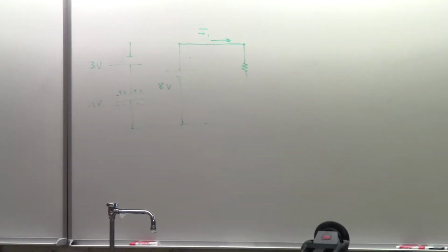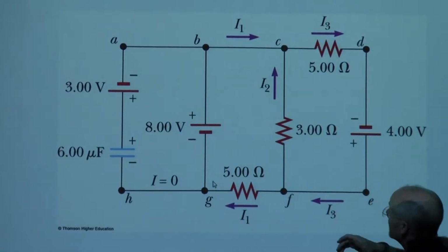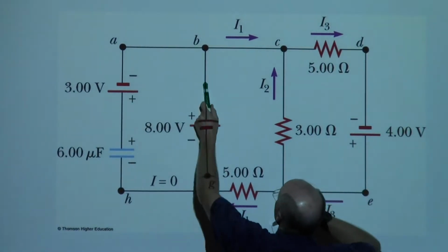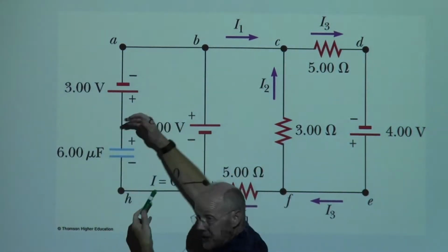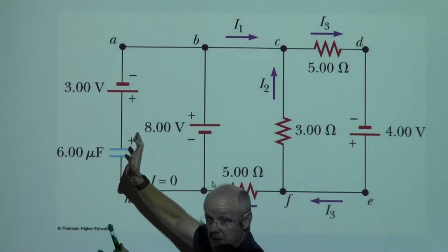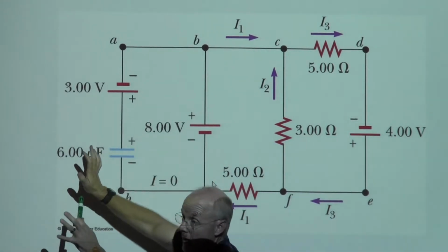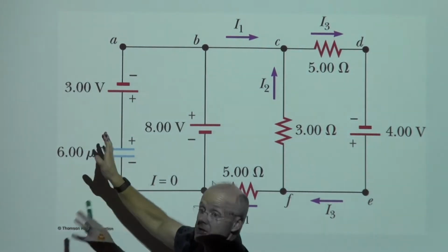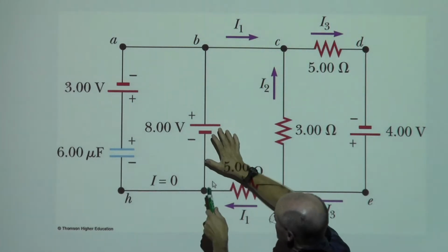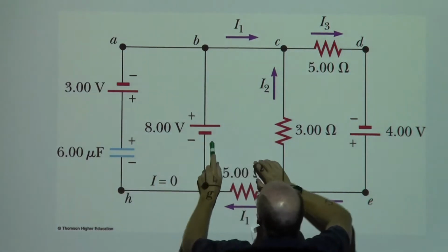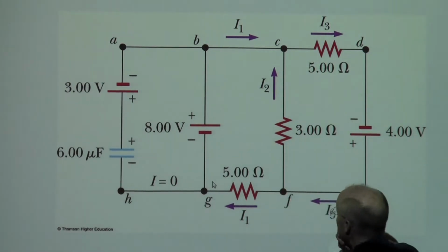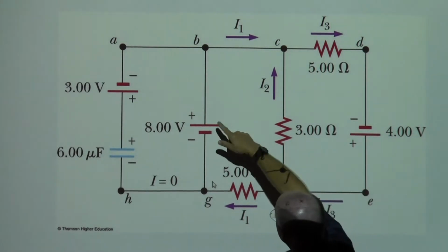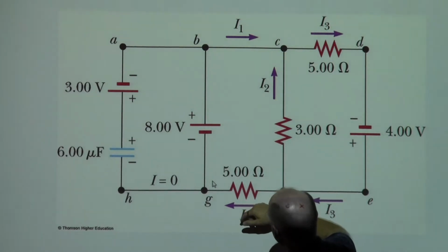As I study the rest of the circuit, I'm kind of looking at this going, all right, this battery is tending to send current that way. Also that way. And it did for a while until the capacitor got full, but after several seconds, it's not sending current that way anymore. So whatever it was, it is now stopped. So the current has been changing here. But after a long period of time, the current is just going this way, which your author calls current number 1. Okay, that seems to make sense. So I like the direction he picks here.